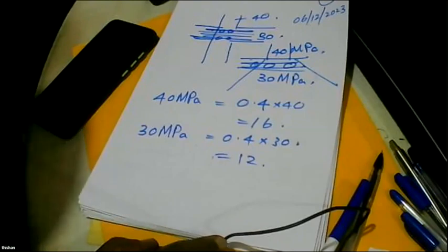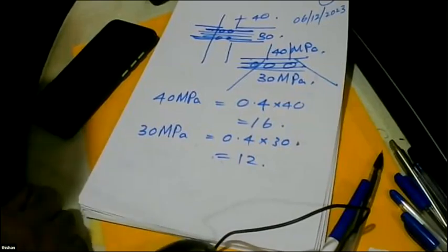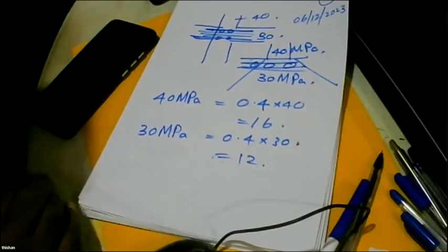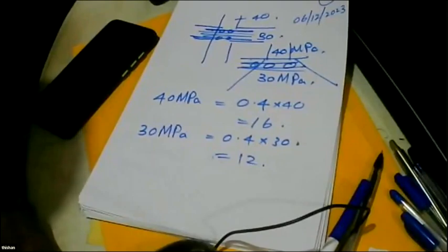No. What I say is, a huge amount of research has gone into concrete mix design, because nobody could get it right. Because of that, I developed a simple method, which is purely based on logic. That's why I showed you how I manipulate the numbers. I know only two things. One is cement is the friend. What is the enemy? I manipulate the enemy. The moment I manipulate the enemy and make it as small as possible, I can bring the cement content down in a drastic manner.